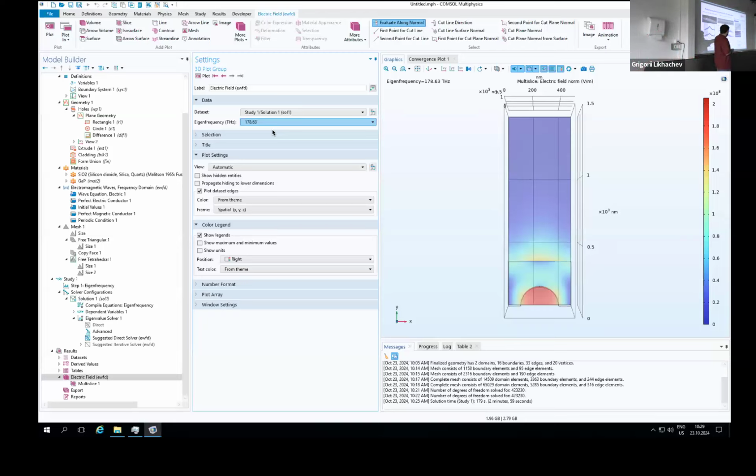This in the middle is my work for gallium phosphide. As you see, I'm using these holes in the waveguide. In silicon nitride, people are using mainly this external modulation of the sidewalls. What I want you to focus on is that for the silicon nitride, they had intrinsic quality factors of about 4 million, but the mirror was non-chirped. That means that they just picked the dimensions and repeated the exact same unit cell for 100 unit cells. So that gives you high reflectivity, but for a narrow frequency range.